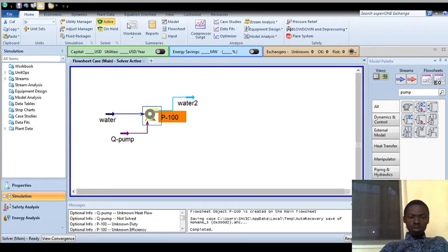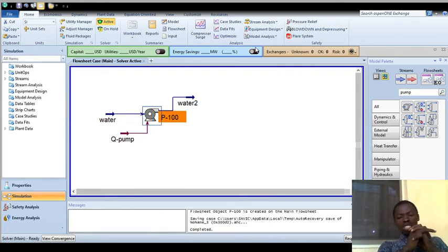So now in order to do that, you can do it from here, you can do it individually. So let's do it from our pump, from the worksheet. Now the new outlet temperature is 200 degrees C. What is the efficiency? So your outlet temperature is now 200 degrees C. Hit enter, and what happens to your system? Okay. Do we get that?